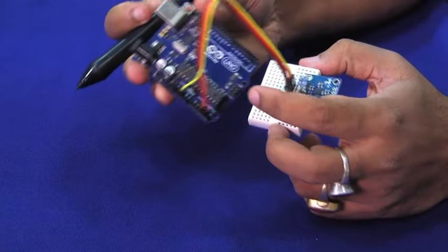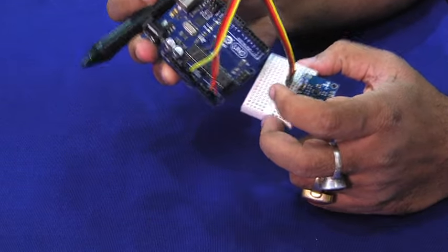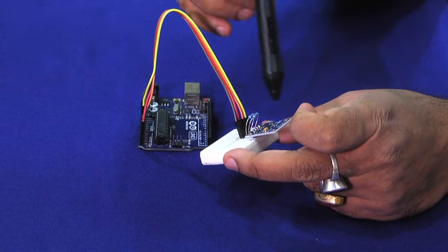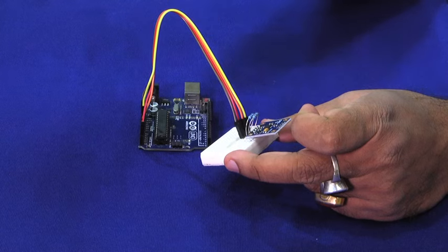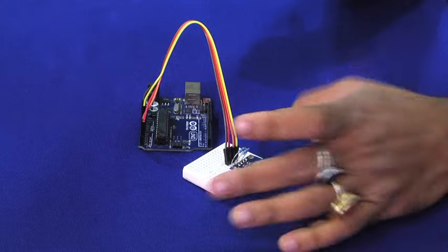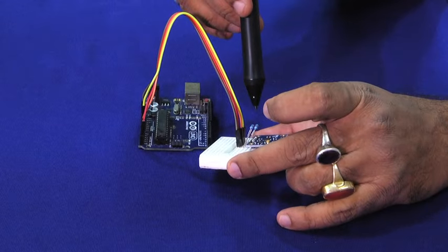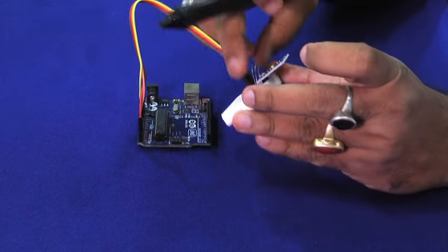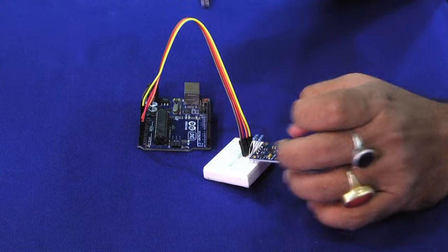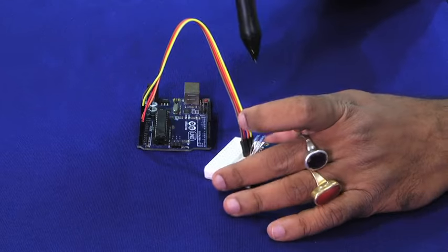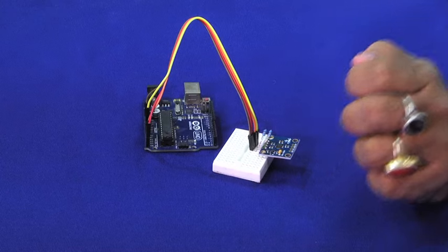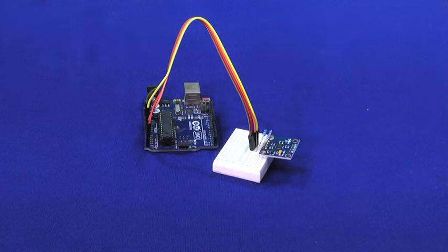You cannot see it very well because it is very small in size, but what I would like to impress upon you is that you can get any of these different sensors and look at their pin configuration. If it is open hardware, you can easily get access to these pin configurations, and from them you will know which pin connects to which port of the microcontroller. Then you connect the sensor to the microcontroller in this manner. This is the accelerometer sensor.